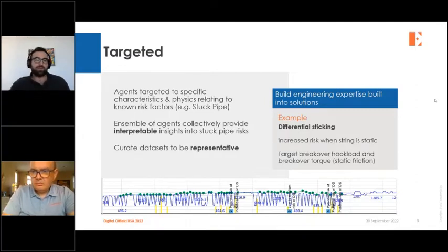Yeah, you probably have something which is packing off the pipe, right? There's a flow restriction and a physical restriction. So based on looking at all those three different factors, which are reliably flagged by the software, you can think, okay, this is probably a pack off situation. And then the mitigating actions that you would need in different types of stuck pipe situations can then be correctly chosen because you have a good view over what the interpretation behind a risk is.